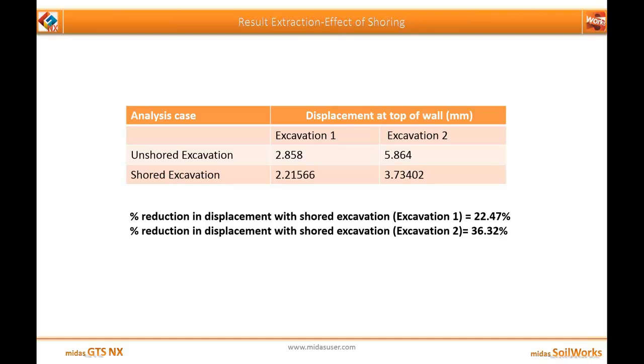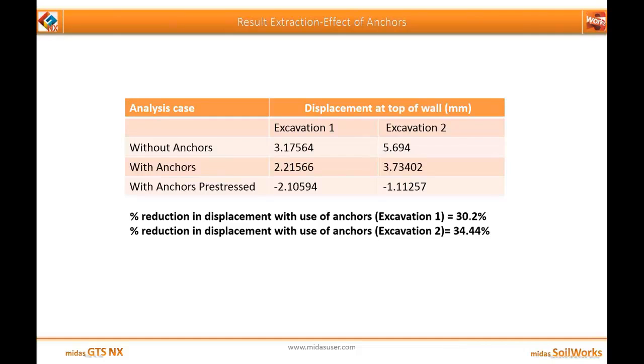Similarly, the second is the effect of anchors. For the same model I have considered 3 cases. First, without anchors, that is only the retaining wall is there. The second is with anchors, and the third is with pre-stressed anchors. You can see that between without and with anchors, the percentage reduction in displacement with the use of anchors was around 30% after excavation 1, and around 34.4% after excavation 2.